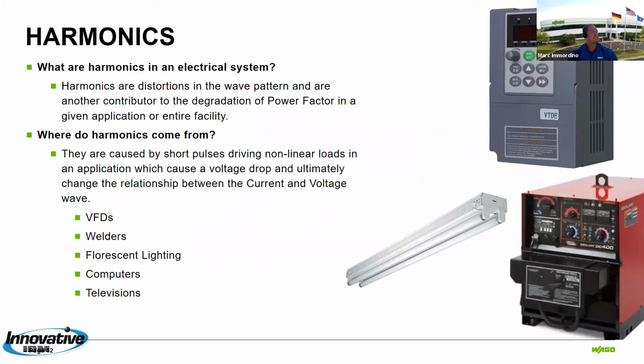So another thing to consider, not just power factor and everything, but also harmonics. These are distortions in the wave pattern that are another contributor to the degradation of power factor. The sources of harmonics can be things like VFDs, welders, fluorescent lighting, computers, television, things like that. So all of these devices can cause harmonics within our system and our power.